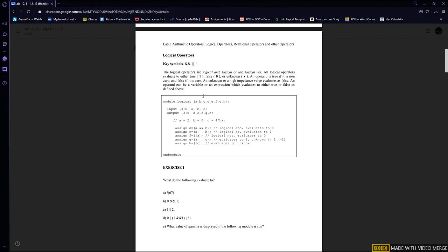Similarly, first of all, I declared the variables. As you can see, after that I declared that the three variables A, B, C will be the input ones and D, E, F, G will be the output ones. While making a graph, as you know, I have shown you the graphs after the simulation in the screenshots while simulating it on Quartus. Those graphs will tell us that these variables are the output variables, so they show the graph of the output values obtained after running the program.